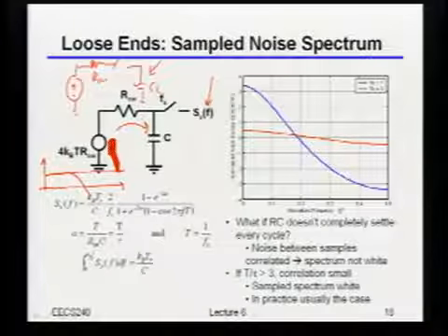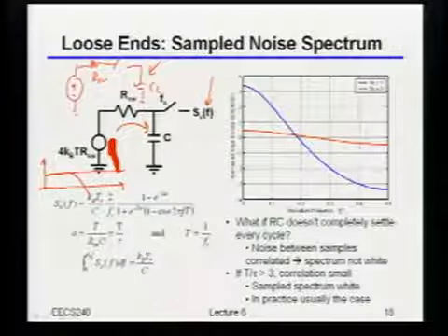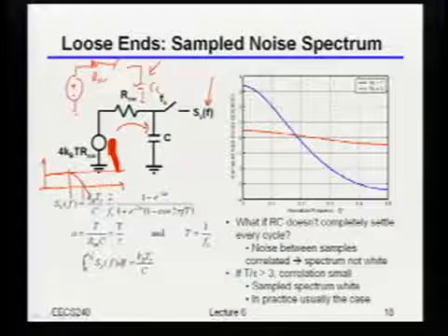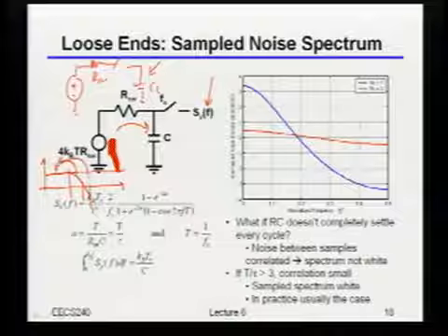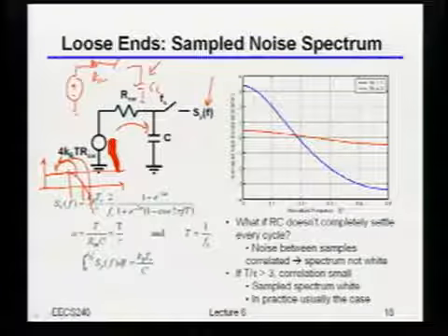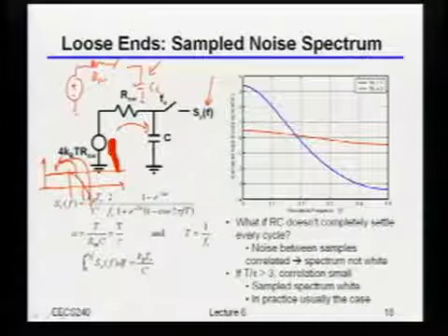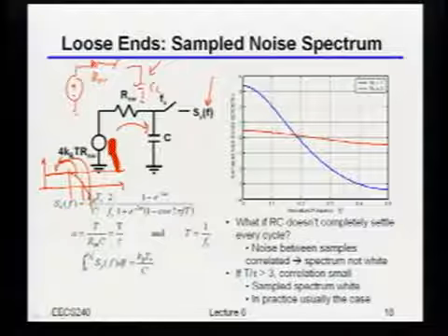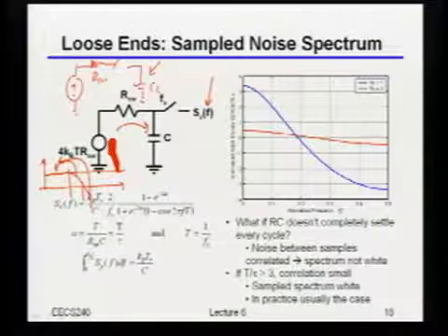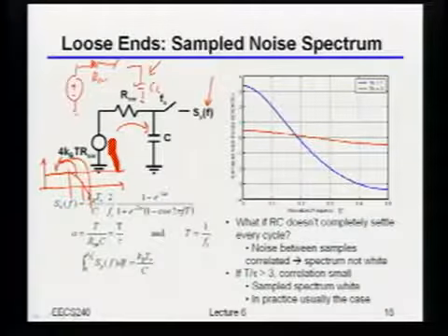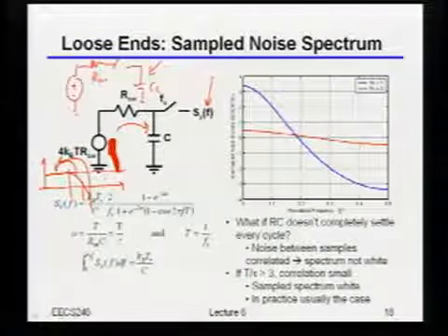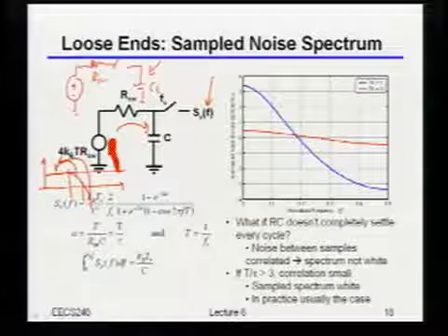Yeah, so whenever you sample something, what you're kind of doing is you take pieces of that signal and fold them back into the so-called Nyquist band. The Nyquist band is basically the sample rate divided by 2. So every sample rate divided by 2, you take that spectrum and fold it back over. Okay, so now you can actually get some interesting effects.